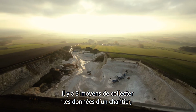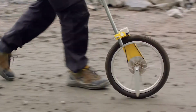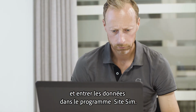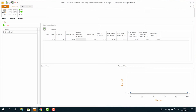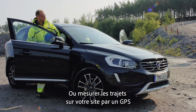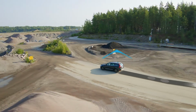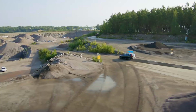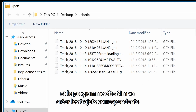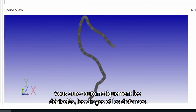There are 3 ways to collect data from the site, which is necessary to get the most accurate simulations possible. Manual input. Measure the current routes manually and enter the data into Site Sim. Or let a GPS measure the routes on your site. Connect the GPS to the computer, and the Site Sim program will create the corresponding routes. We get grade, curves, and distance automatically.